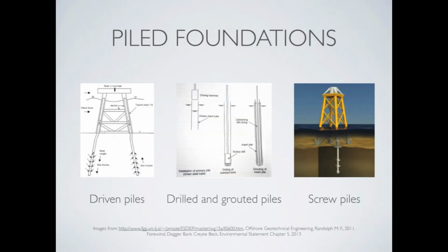Deep piled foundations are often used when soil strength increases with depth, which is the case on site. We considered 3 types of piles: driven, drilled and grouted, and screw piles. After thorough research, we believe driven piles would be the most adequate option for our situation. Driven piles are by far the most used foundation option for offshore structures.